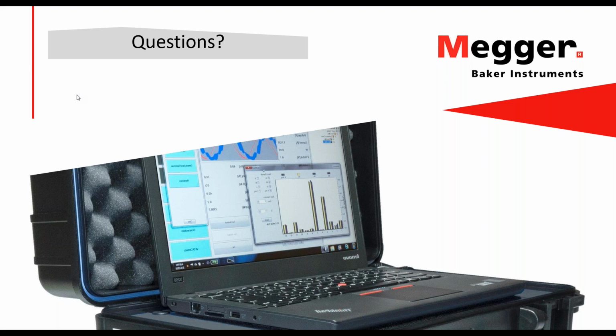But the online test, in fact, the one that you see on the screen now is the EXP4000, and it comes with, of course, the voltage and current sensors to do the testing with, and also presents with the same kinds of parameters as that of PDMA. So online testing of power quality type stuff and spectrums. However, I don't believe they have the torque element, which we do have, the torque ripple and instantaneous torque, which is again key to identifying mechanical issues through voltages and currents.